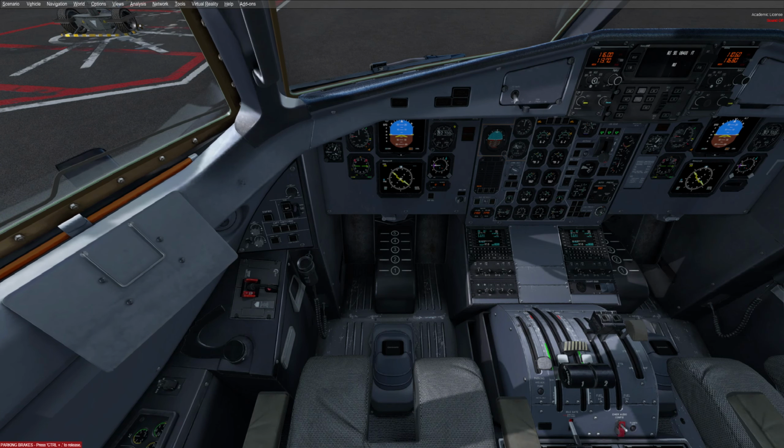What else are we going to look at here? Ceiling is 24,000. It's got a really long range. That's good. 700 kilos of fuel will be used the first hour, and 600 kilos of fuel on average every hour after that. So if you need to figure out your fuels. Descent indicated airspeed is 230 to 235. That's what you want to aim for.